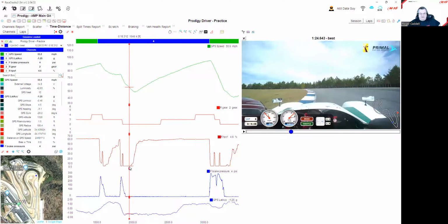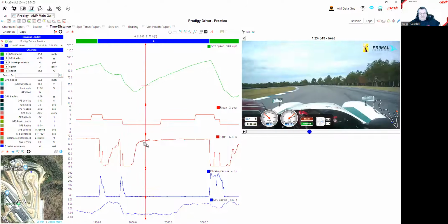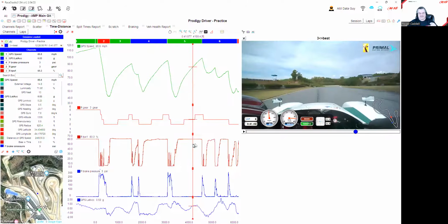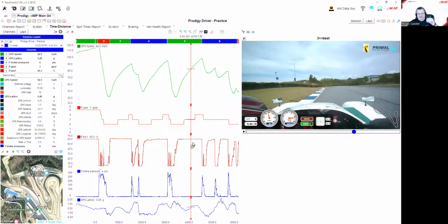The driver goes to throttle up, and then sits there. And by the way, this throttle position trace, while I'm going to zoom back out, you can see that it's definitely at full throttle. There's a flat plateau across the top. The data shows it as only 60.3. Don't get hung up on that. It's not 100%. It's clearly the driver has it to the floor. And then so that's your new baseline, right?